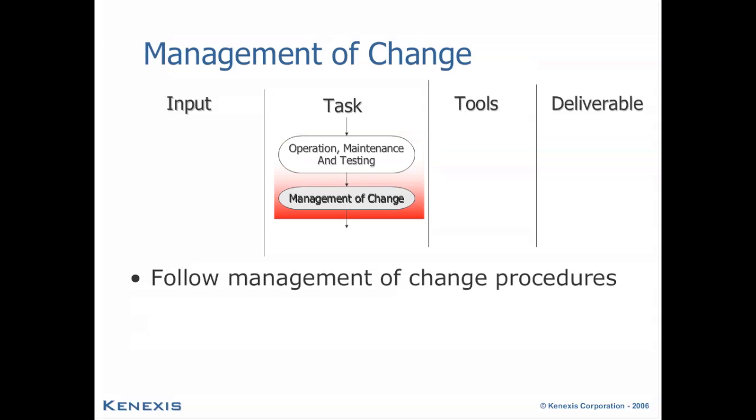Most companies do have robust change management systems that are required under OSHA process safety management, and any changes proposed to the safety instrumented system, changes that are non-like in kind, would typically be required to follow those management of change procedures to be assessed prior to implementing any changes, to ensure that all functional safety aspects are being achieved and that we haven't compromised in any way our ability to achieve the desired level of integrity.